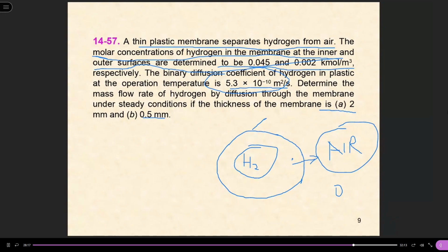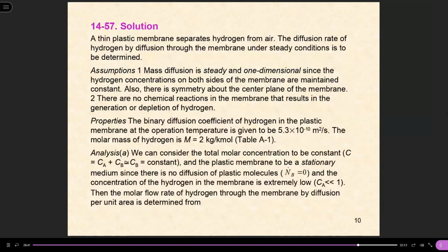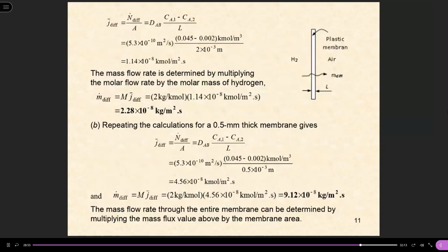But this tutorial is tricky. They already told you the mole fraction within the membrane. In reality, you don't know, but in this question it is given, and then the calculation becomes very easy. It has a lot of discussions here, but you can almost ignore them. The final calculation is such an easy calculation. Here you don't involve the so-called solubility, because you only involve the parameter within the membrane. So solubility is not involved, only the diffusivity.